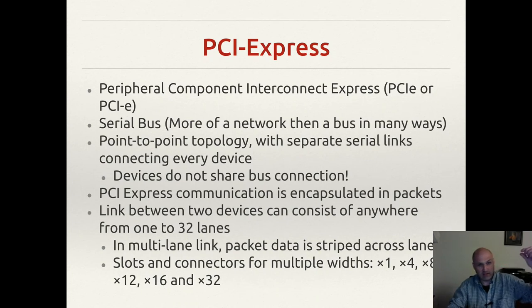But if the length of that one can be, say it's an 8-bit bus, just for an example, and let's just use raw numbers. If, say, the length of this one was 10 times shorter than the longest one, then you could technically, with no other advantages, which serial does offer, transfer 10 bits in the time that you could transfer 1 over that longer line.